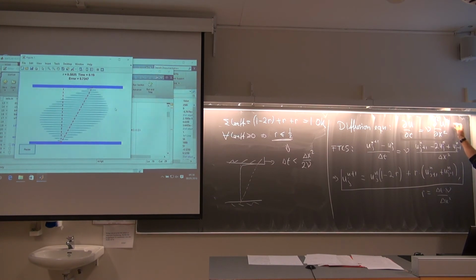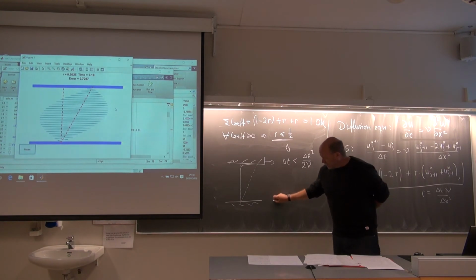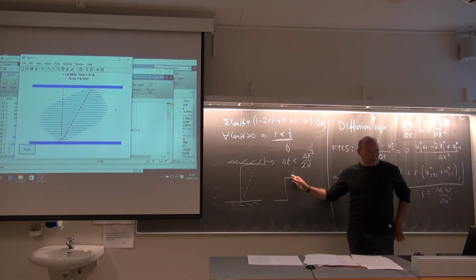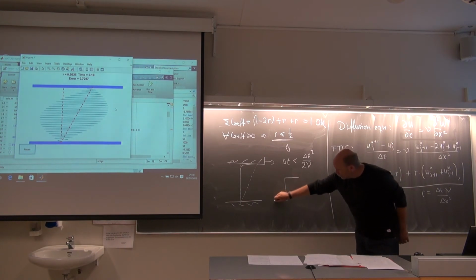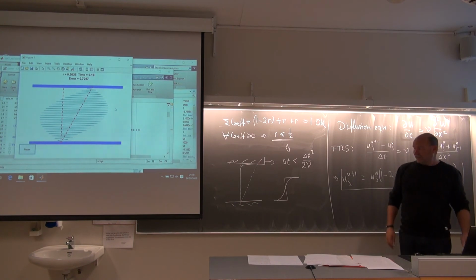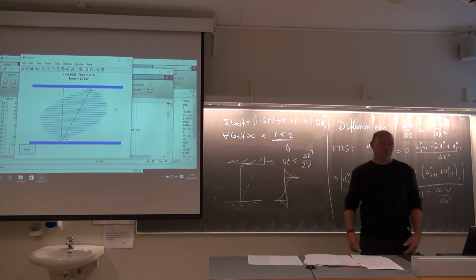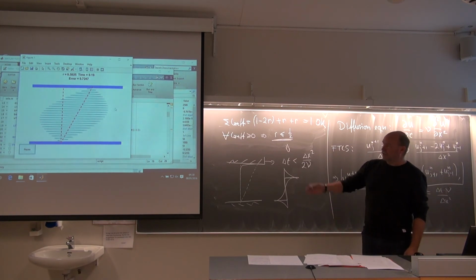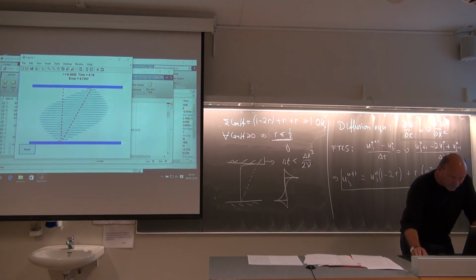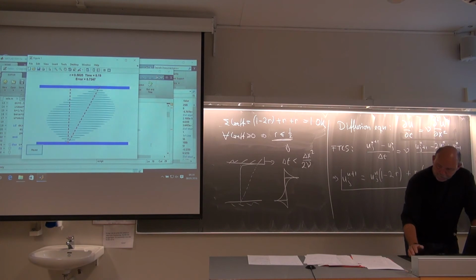And a negative diffusion, that is dangerous. What does a diffusion mechanism do? Well, if you have a sharp gradient, a jump in a quantity, it will tend to smear it out. That's positive diffusion. Negative diffusion does the exact opposite. It will explode. So this is what happens here. You'll see more of this later with numerical diffusion, as we call it.